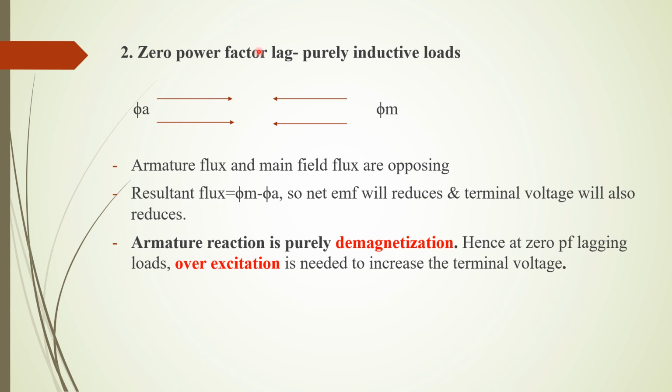Okay, we will discuss purely capacitive loads in the next slide. So here in purely inductive loads, power factor will be zero power factor lag, and here phi A and phi M, both of them are opposing each other.